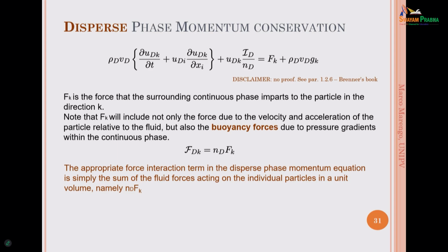About the forces in two-phase flows, which was the other one? Due to the difference of density, we have a buoyancy. The buoyancy forces are really important in this case because, for example, with bubbles in gravity, of course, when the bubble is moving inside the system, we need to understand this.